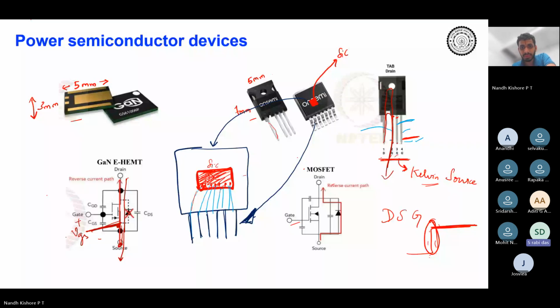But when you are giving the PWM pulses or any gate pulses to the FET, if both are separated, then with respect to Kelvin source only we have to provide the gate pulse to the FET, correct? And we can give the high voltage or power source with respect to this power source line, correct? So in that case, both these two sources, externally you have to short them?